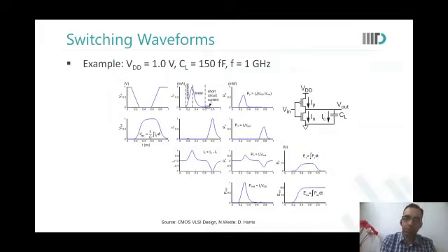So this region in the curve, I'm not able to get exactly. You tell me, what is happening here? Is there any change in the output voltage happening here? This is V out, no? Is there any change in output voltage happening here? No, sir. So if there's no change in output voltage, why should there be current flowing from either the PMOS or the NMOS? Yes, sir. So that is what it is reflecting.